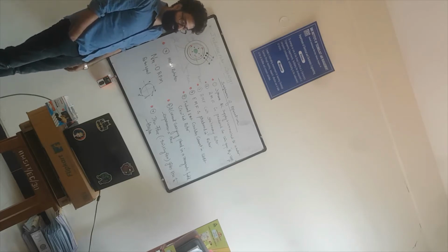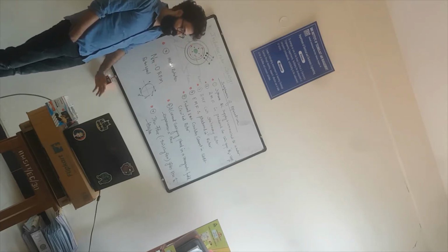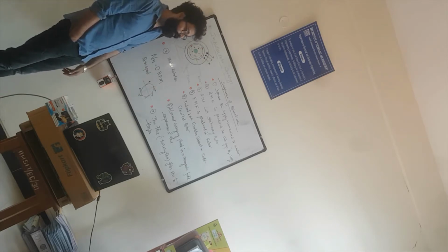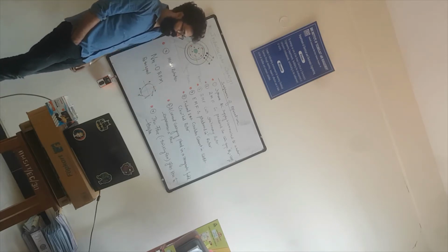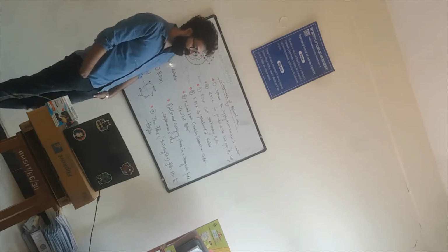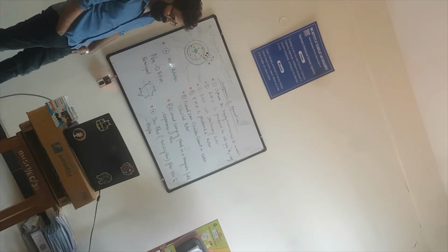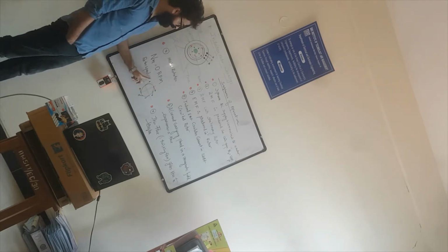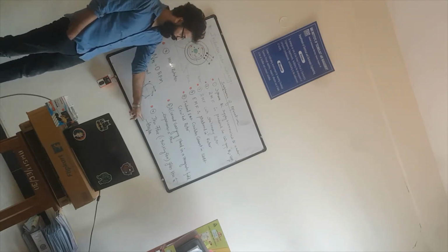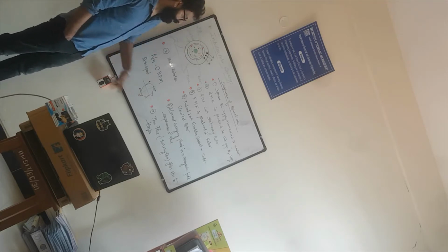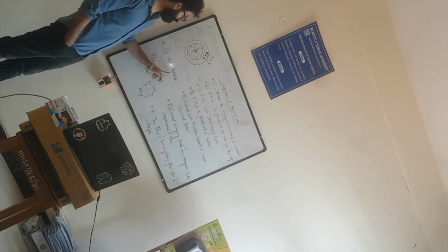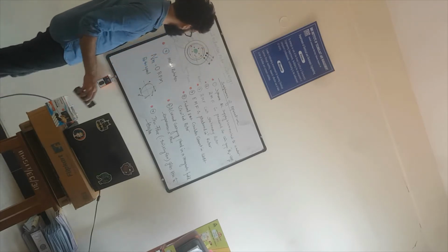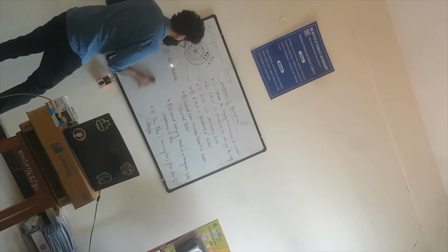The rotor is a closed circuit, hence currents start flowing into the rotor circuit. A current carrying conductor placed in a magnetic field experiences a force, acting tangentially on the rotor surface, due to which a torque is produced, and the motor starts to rotate. So this is the working principle of the induction motor.